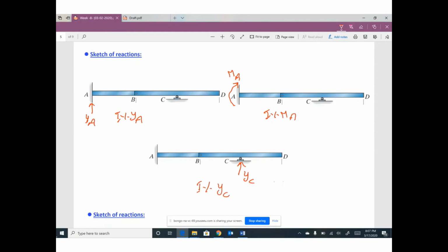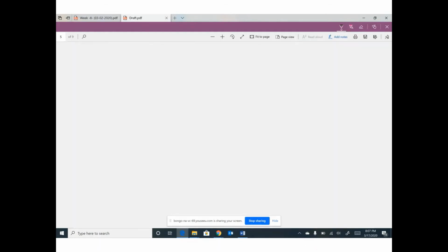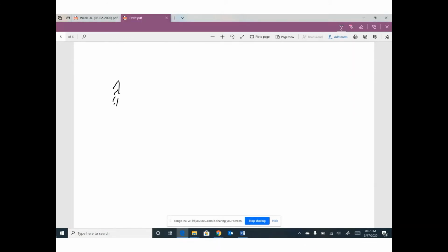I would like to remind you for something. You have fixed it. And I would like to draw influence line for reaction and influence line for moment. Your moment is assumed to make your member to smile. Okay. If you push this support up by one, this part of the beam which is attached to this fixed will move up.